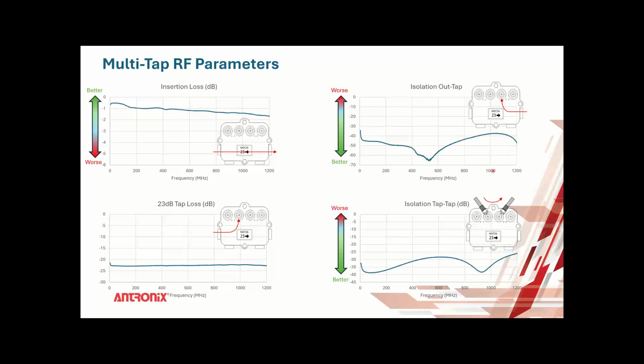Yes. And as you can see, the isolation is not a uniform straight line. It varies with frequency, so you should check the vendor's specifications. They typically spec the worst case. So this tap may be specified at 30 dB worst case, where everything's at least 30 dB, and typically it's better than that. And there's a curve associated with isolation.